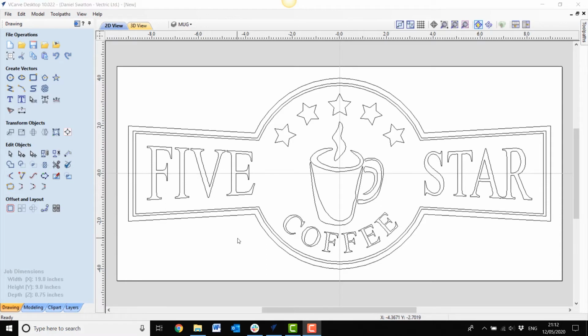However, before we actually go ahead and create the toolpaths, we ought to really address the design concerns that we looked at earlier. On question 1, can I create a vector design directly in the software? Well, the answer is yes. You've got the full vector suite such as lines, shapes, text and dimensions. You've got the simple intuitive skills such as smart snapping and quick keys. You've got the rapid design tools such as offset, weld, wrap text, scale, copy along vectors, distort, and of course you've got the easy management with the use of colors and layers.